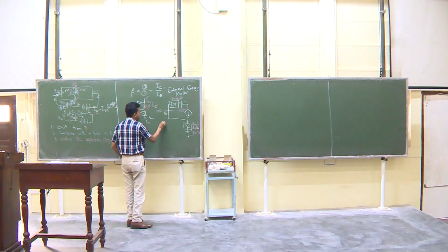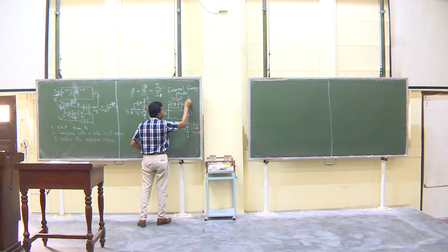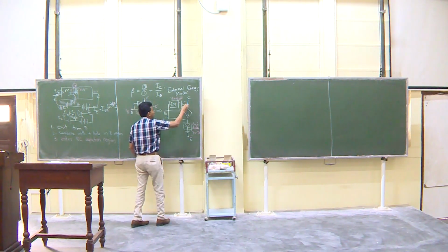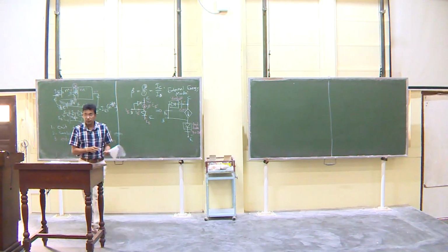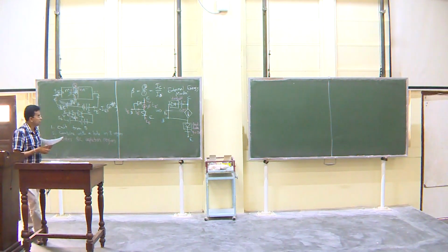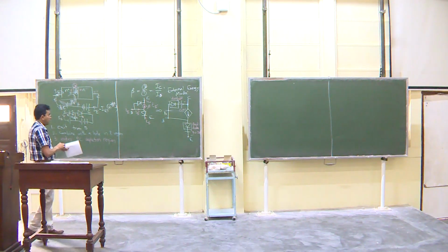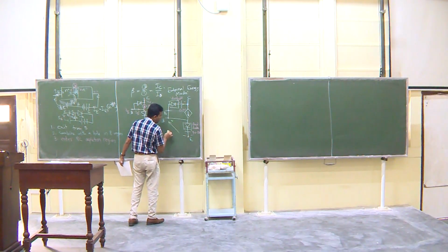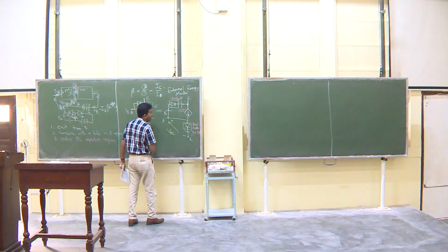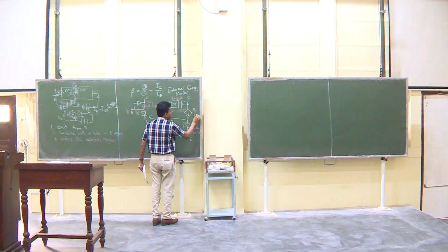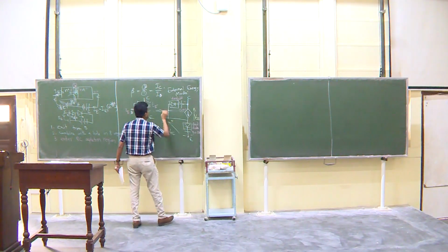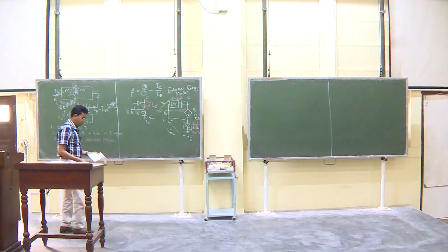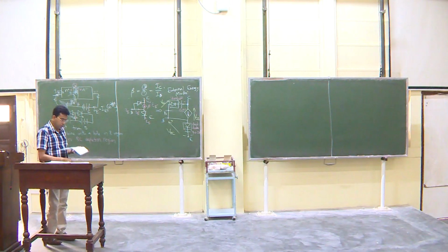Okay. So, this is basically what we ended up with. So, we had the base, collector and the emitter. So, these are the three output terminals of an NPN BJT transistor. This is what we looked at, and the voltage between this and that was VBE. This is VCE and VBC, right. VBC we do not typically care much about.